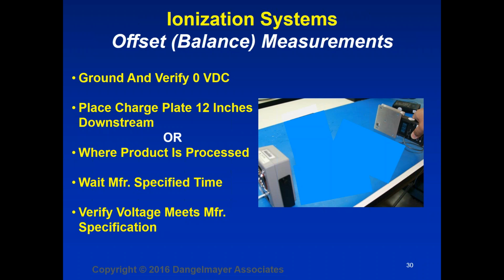Other ionizers don't have that adjustment capability. Something in their design is meant to keep the voltage within the manufacturer's limits, and if it's outside the limits and it doesn't respond to cleaning, then you need to send the ionizer back for repair.